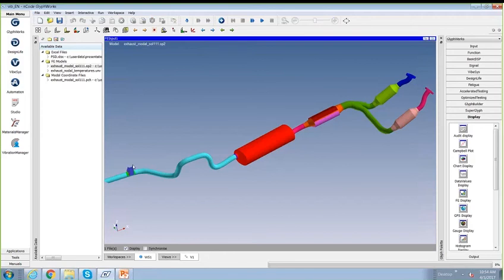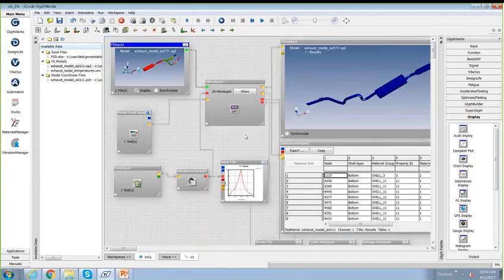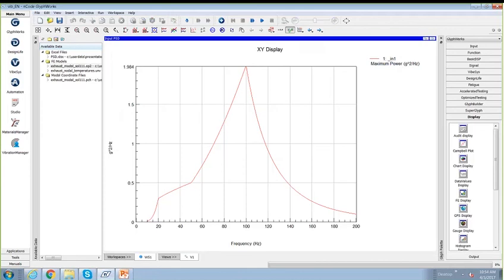In this case, we're looking at strain life. And so what I have is an input PSD that I'm applying. This is a PSD that I have specified I'm going to apply to the hanger.